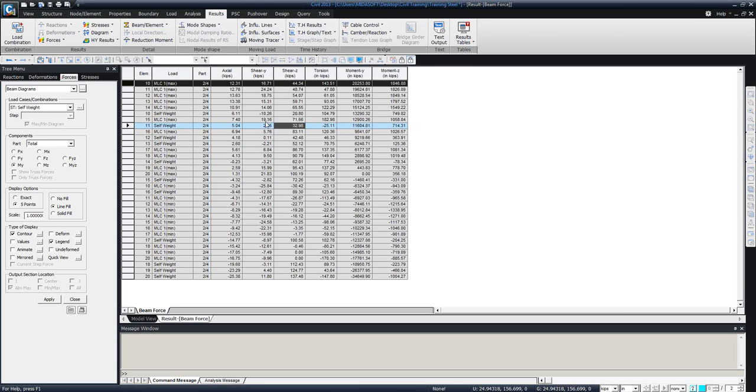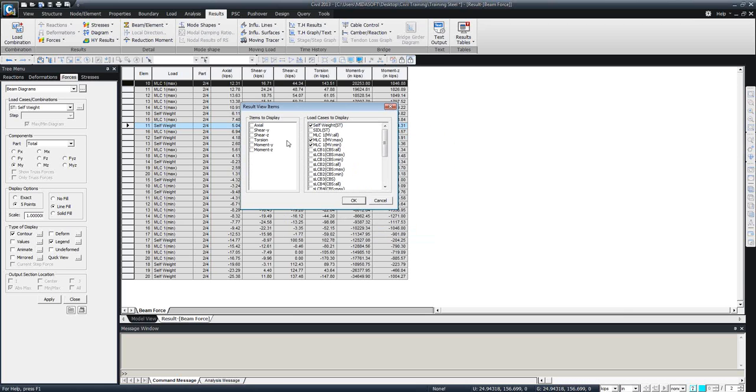But here's the thing. Now, under the moving load analysis, you see there is an axial force, shear, and torsion and bending. But these components are not happening at the same time. These are just the extreme results. They are like a maximum or minimum result. But to see the concurrent forces, just right-click on this table and go to the view by maximum value item. Just click on that. It's going to ask you what values you want. Let's say I want just the axial force and then the bending moments.